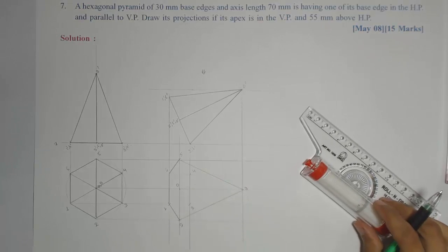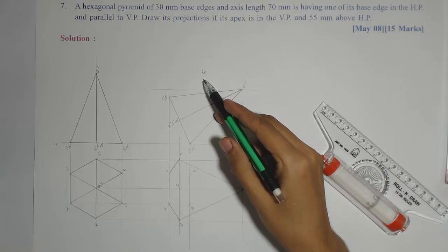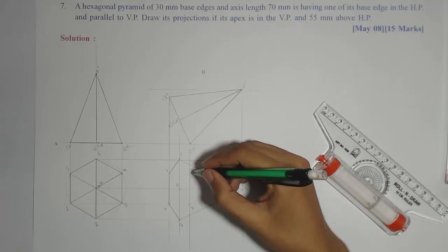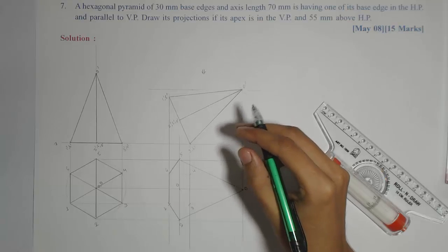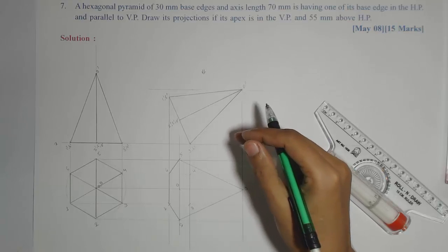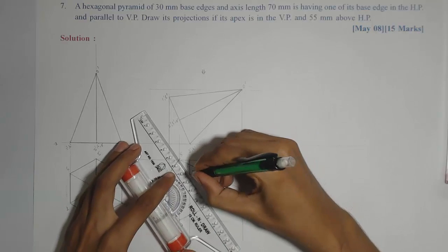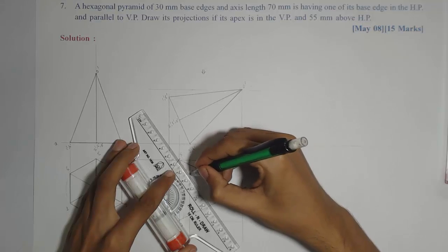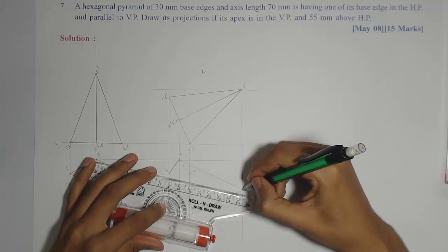Okay. Now 3 dash, 4 dash, both the corners are away from the observer. So all the 3 edges starting from each of points 3 and 4 should be initially marked dotted, and if any one of the edges lies on the boundary, then it should be made dark. But here if I draw the 3 edges passing through 4, there will be one base edge O4 that should be dotted, and since it is not lying on the boundary, it will be kept dotted only.